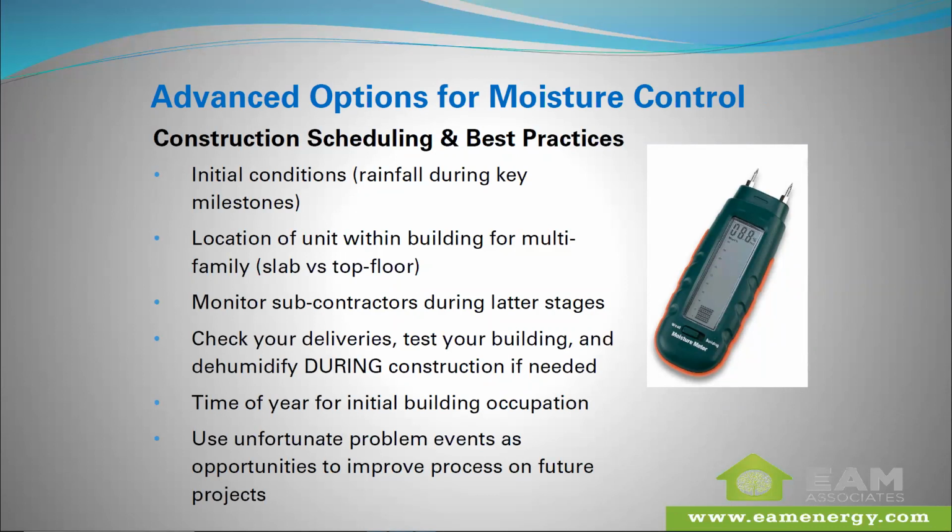Location within the building is an issue. You're going to have more problems with this on the slab level than you are on the top floor. The top floor unit has more load on it, but then also the slab is an issue. Construction moves at a very rapid pace these days. Slabs generally are not allowed to fully cure. People pour the slab and they go vertical. You guys know some of these builders move fast and you're enclosing these buildings quickly. The slab is still putting off a lot of moisture. So that has to be monitored.